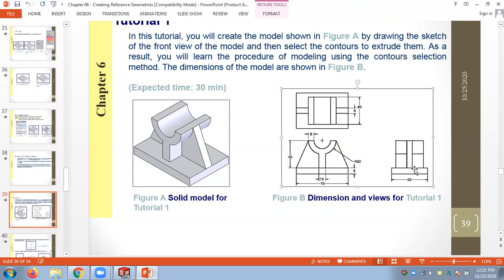When it comes to this kind of drawing, what can we do? We have the extrusion method, the revolve method, and the sweep method I just introduced. What is the 3D method I am going to use for this model? That is the first thing you have to understand. I cannot use the revolve tool here; obviously it is not going to work. Even in this one it's going to be difficult. The extrusion tool is the tool I am going to use.